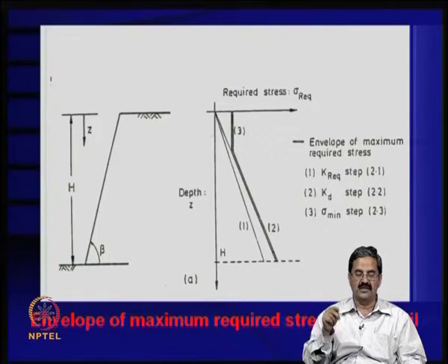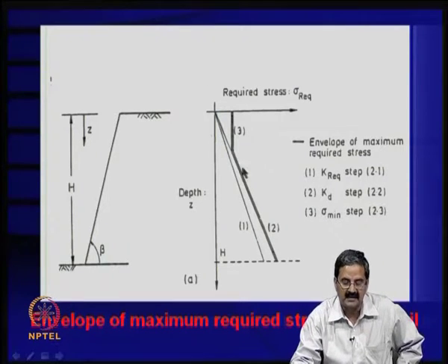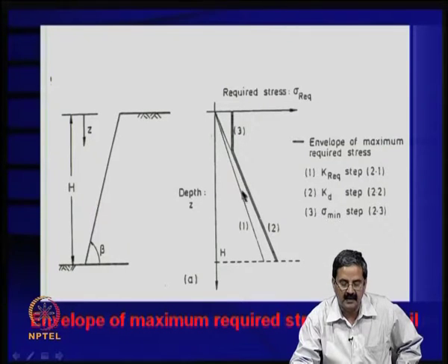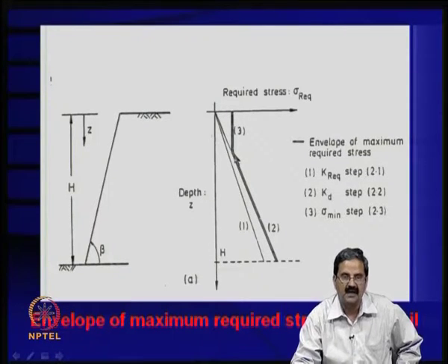So we assume that the whole force is acting, but there are some small changes here. From bond and reinforcement angle considerations, there is a small correction factor you have to put in, because of which the required reinforcement force will be a little higher.